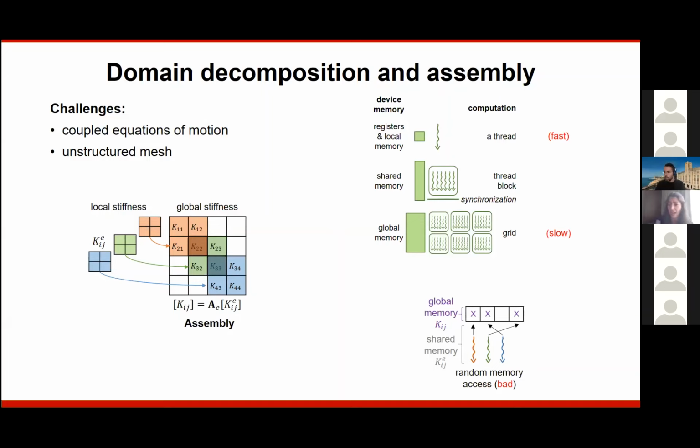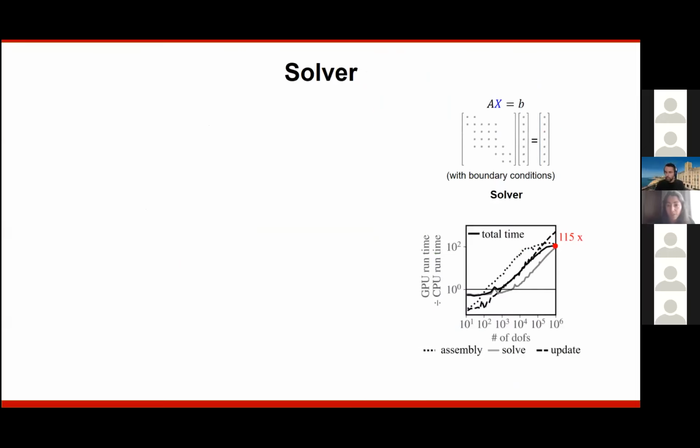You want to make sure that as you access that global memory, you have memory coalescing, where basically when you have global memory access, everything is aligned and sequential. What this requires is complete restructuring of the information in your mesh prior to even performing the analysis. And this is huge when it comes to performance on the GPU, making sure that memory access is as fast as possible and sequential and aligned.